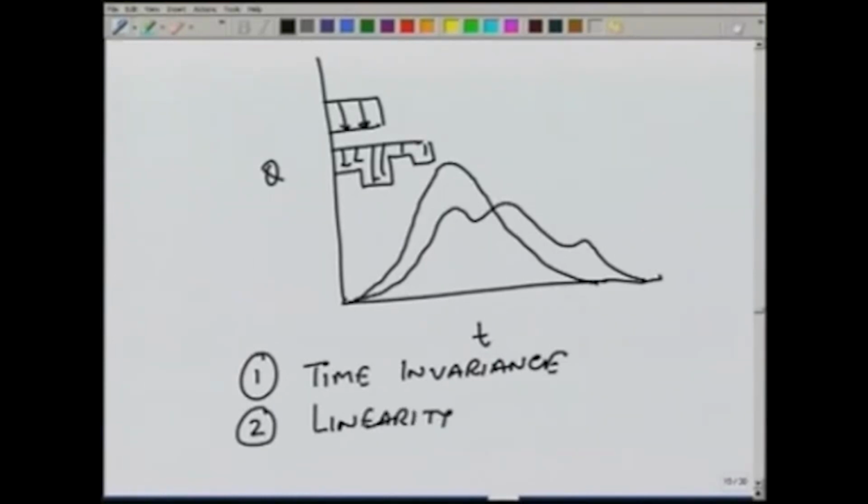In general, rainfall runoff relationship is very complex. If we have two different catchments, the same rainfall will cause very different hydrographs, or for the same catchment, if we have two different kinds of rainfalls, they will also cause very different hydrographs. Sometimes even for the same catchment and same rainfall, we may get different hydrographs. It depends on the initial conditions.